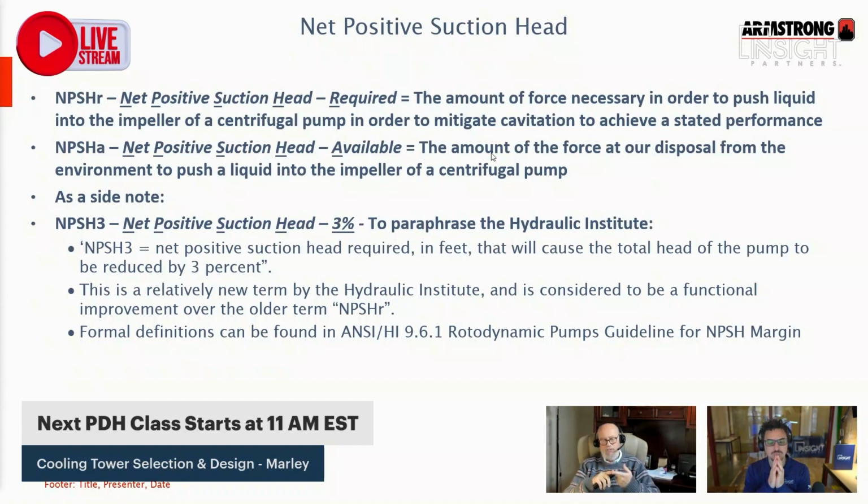I can't control system cleanliness. As good as all of you may be as an engineer, there's no way you can control how clean that system's going to stay. You can't guarantee that the owner's always going to clean those pump strainers on the suction side of that pump every week like they're supposed to on a tower system.